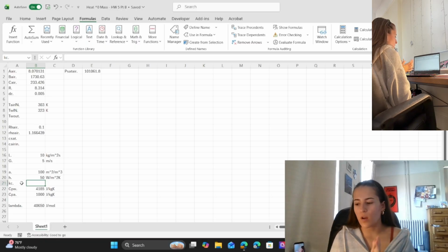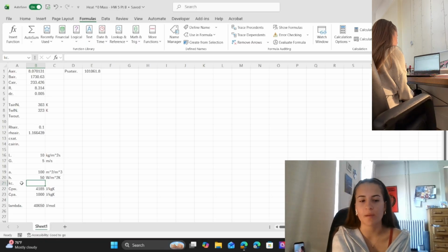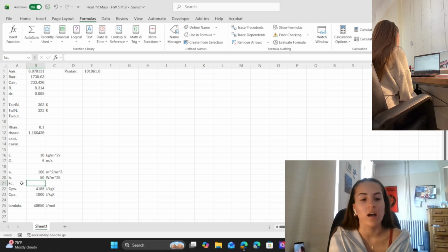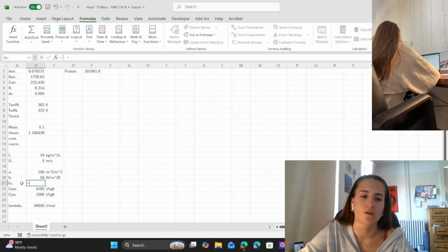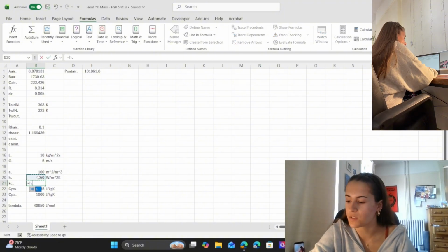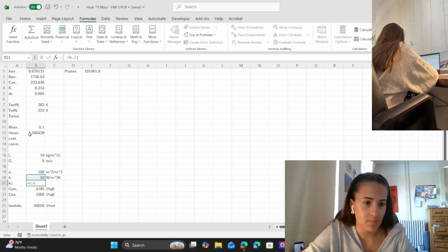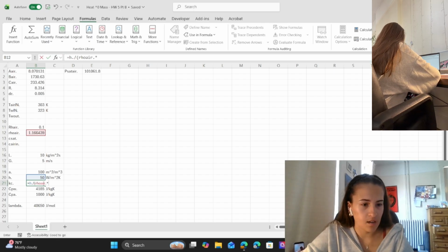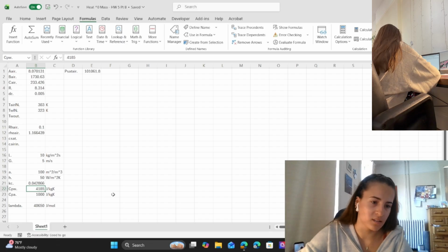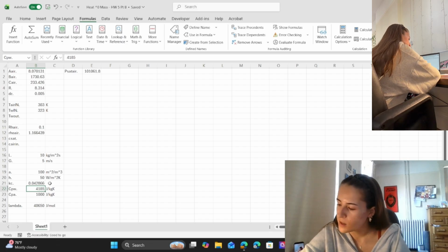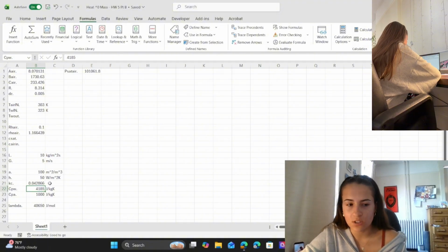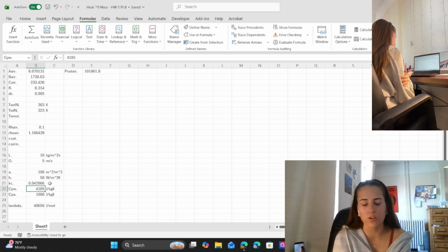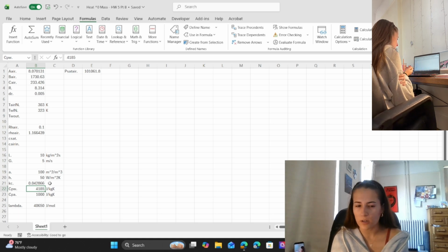And so in our equations over here we had solved by plugging that in, but just to make it a little simpler for actually plugging into the Excel, we're going to go ahead and solve for this over here using that equation. So if you recall, that's going to be H divided by the rho air times the heat capacity of air. And so that will be our value for Kc, which is related to our Lewis relationship again. That's how we get that equation. And then we're just putting that in here so that it's easier to type in all the values later.